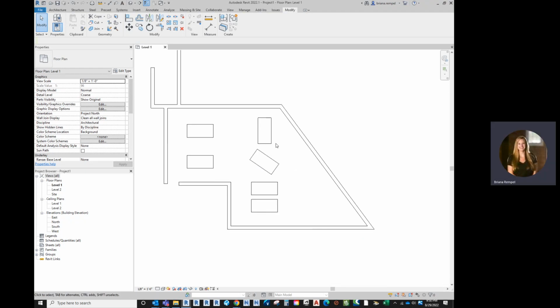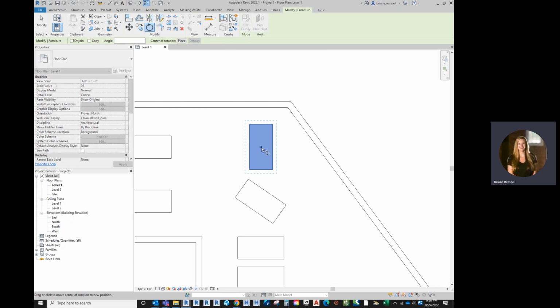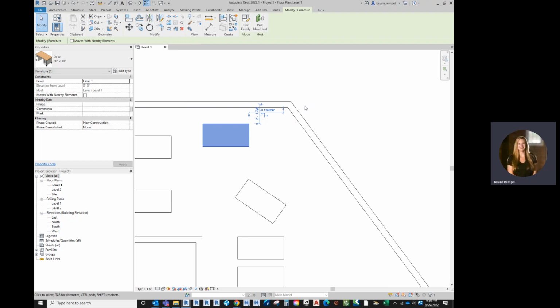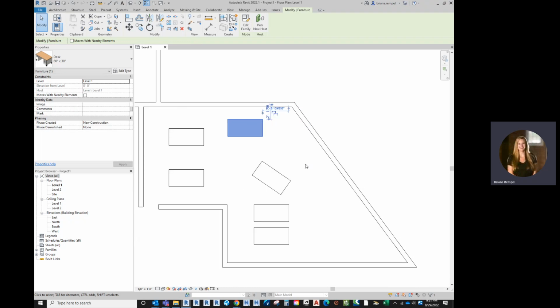This, I think, is a good opportunity to look at our align command. Oh, one more thing on the rotate. It always defaults to the center of an object, but if you wanted to rotate it about one point of the object, you're just going to click on that blue dot and drag it, and then I can rotate it around that corner of the element instead of around the center. So you do have control over where that rotation origin is.